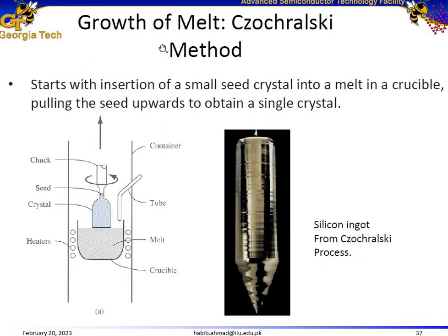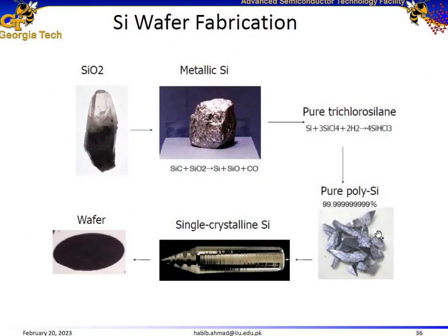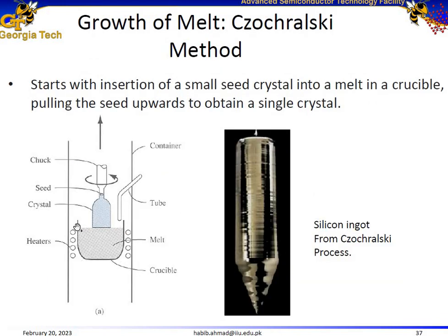Here is the Czochralski method for growth of silicon from the melt. So you take this granular form silicon, you place it in a crucible, you heat the crucible, which is going to melt down silicon, and this process would occur above 1200 degrees C, at a really high temperature. And then you introduce a single crystalline silicon seed into this tube, which kind of looks like a flask. It has a narrow neck, and you keep pulling up the seed from the melt, and you also rotate this infrastructure at the same time. So by rotating and pulling it up at a slow pace from the melt, it results in periodic arrangement of atoms in a single crystalline boule, and this is the end product, which is kind of an upside down version of what is happening over here.